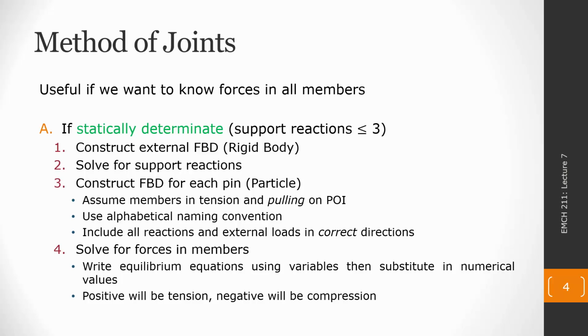If the structure is statically determinate and we drew that external free body diagram, typically we are going to have one extra free body diagram we could draw, but we're not going to need. So typically we're going to have one extra pin FBD we could draw, but by the time we need to draw it, all of the unknowns will be solved for. That pin still must be in static equilibrium, and it can serve as a good check to make sure that we did all of the math correctly, that all of our equations were written correctly. However, it's not going to add any new linearly independent equations to the set that we already have.